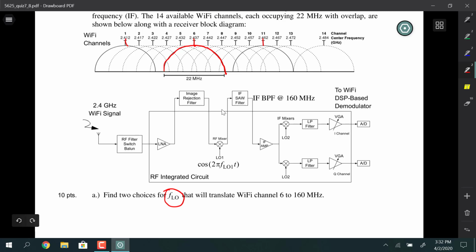I had read an article, I think an IEEE article, that somebody had written on an integrated circuit, an RFIC for Wi-Fi, and I took that block diagram and pasted it in here. It's showing what we need to do to build this. In the block diagram, they show an image rejection filter outside the chip, an LNA in the chip, and an RF mixer in the chip.